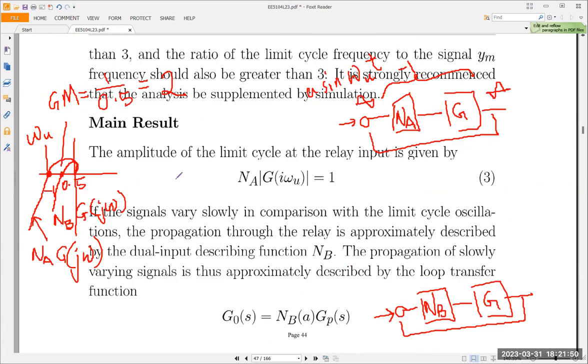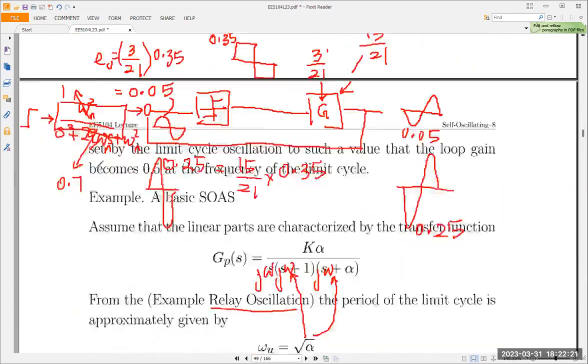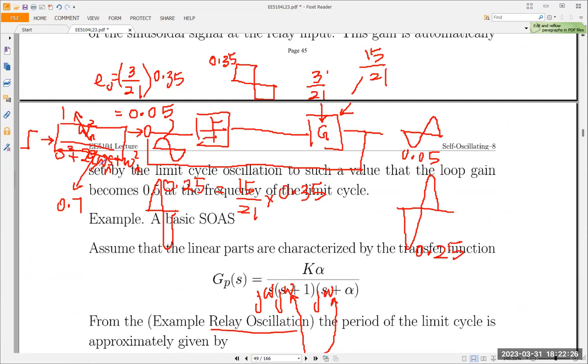If you remember classical control, you will draw the Nyquist plot like that. And then this would be omega u. This would be omega u. As far as AC gain is concerned, the omega u is at -1. As far as DC gain is concerned, or to say accurately, the low frequency signal or the DC signal is concerned, the crossover frequency is at -0.5. Okay, so now the only things can be clear only if we see the picture.